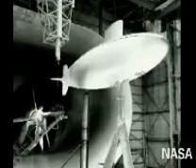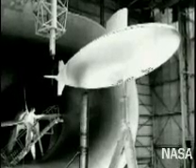Depending on the Reynolds number, some flows have different regimes with different flow patterns. The classic example is the flow over a circular cylinder, illustrated here using a soap film tunnel. At low Reynolds numbers, between about 4 and 40, attached vortices form behind the cylinder.